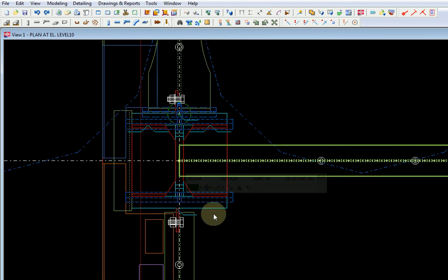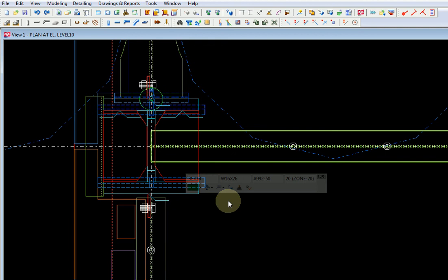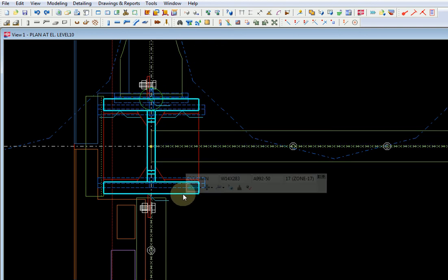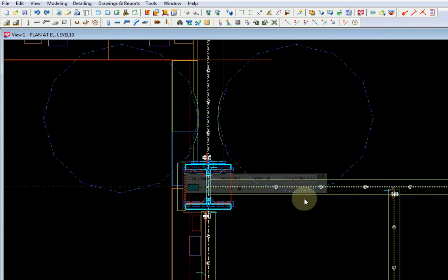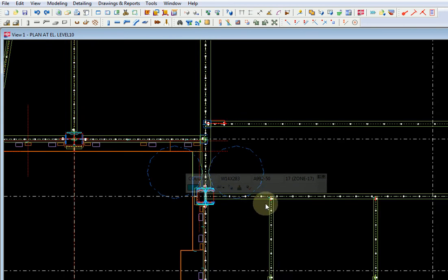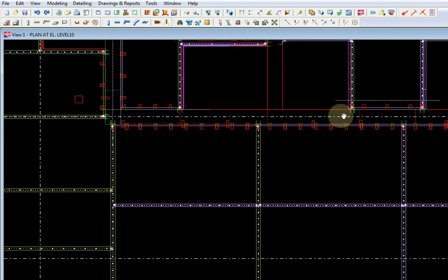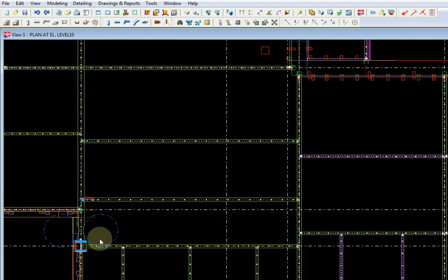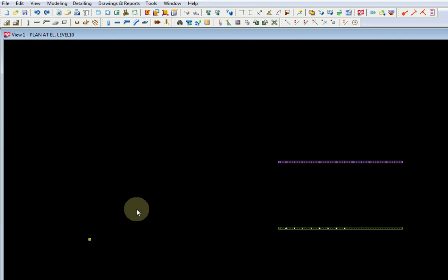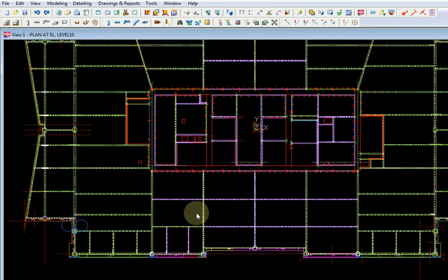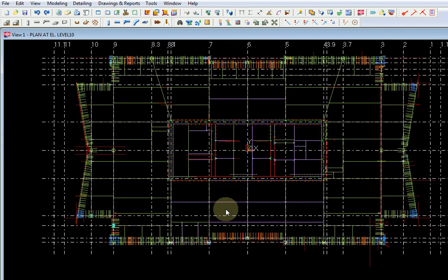I have to use a different setting, a different macro, to pick the beam, column, beam, top stiffener, bottom stiffener. If there is another double plate, I have to pick the double plate, then draw another connection. So I need another hour to manually pick all the connections to the wall and the connections for those pieces. So in 2 hours, I can make the whole level of the building connected.